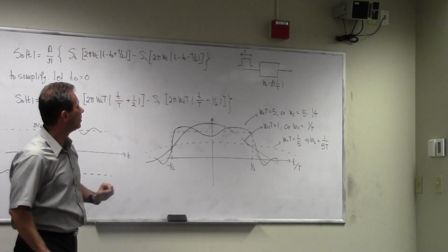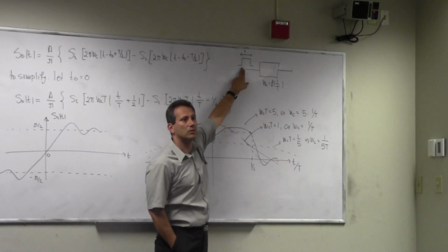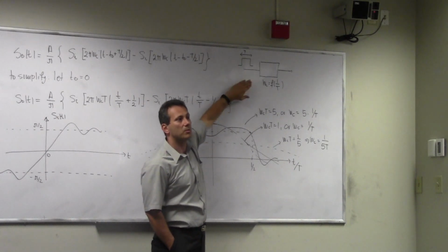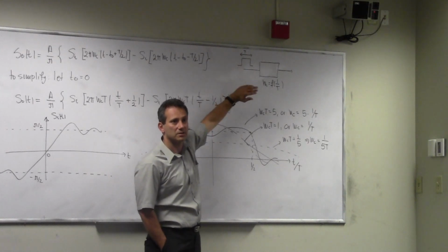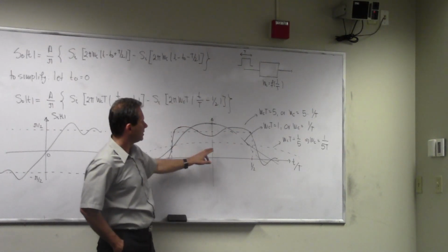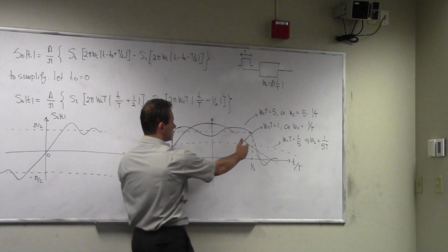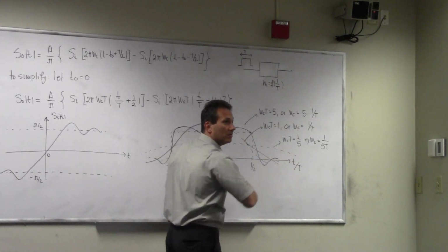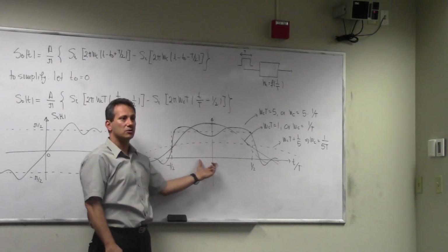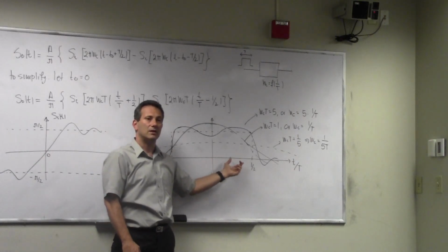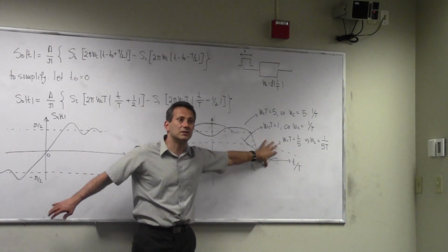Remember what we're doing. In most communication systems, in the simplest way, you're going to use this, for example, to indicate 0, and you're going to use the opposite one to indicate 1, right? So you're signaling with plus or minus. What happens as your bandwidth shrinks relative to the duration of your pulse is that the energy of your pulse gets spread over multiple pulse durations. And this pulse here, which ideally should be between -1/2 and 1/2, now exists before and after, right?